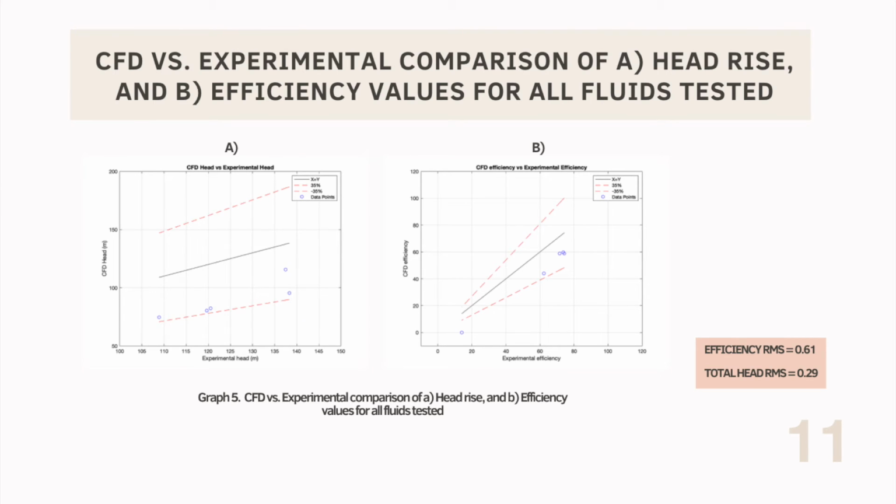In order to visually analyze and make a comparison of how far the data is from the design pump's, such as the efficiency and the head, the following graphs were constructed with the data of the ideal case. In both graphs, it can be seen that most of the efficiency and total head data in the CFD model are within the 35% acceptance region. Additionally, the values corresponding to those of the simulation differ considerably from those reported by the manufacturer because one of the points does not fall within the 35% zone.